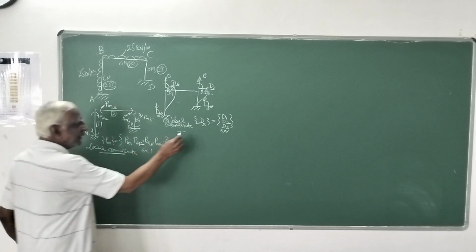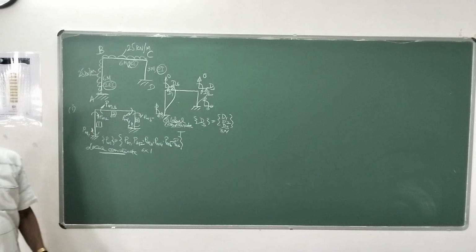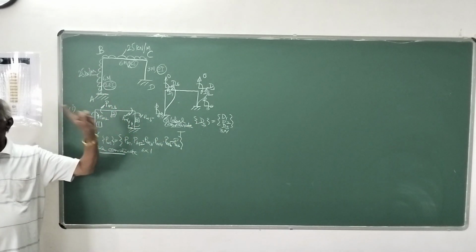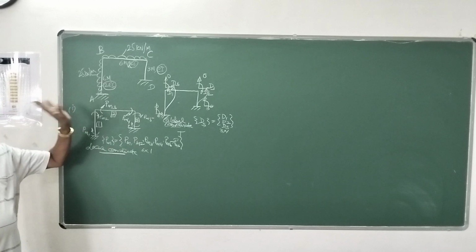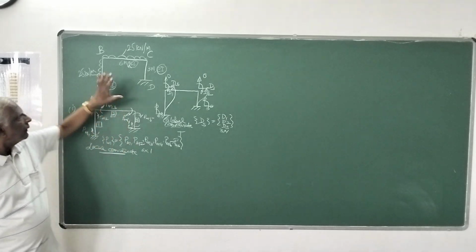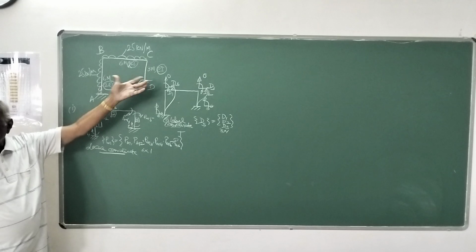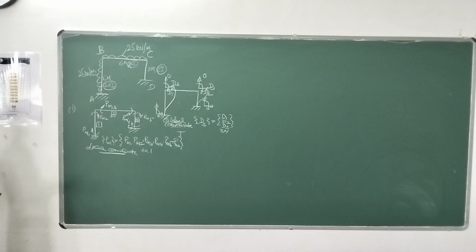Then we have to find out the forces corresponding to this unknown displacement in global coordinate. That force should be acting at the nodes only. But here, loads are given on the members. We have to find equivalent end forces or equivalent joint or node forces.